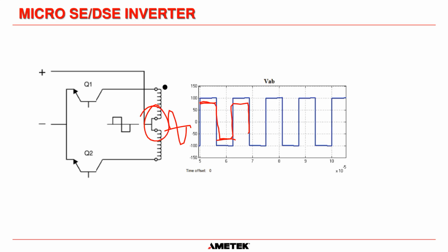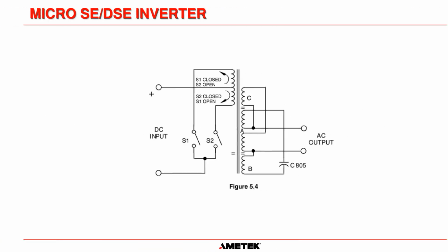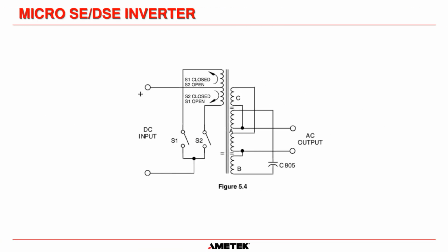So what this transformer does is for the changing DC, the pulsed square wave that goes into the primary of the transformer, although its amplitude will change, the amplitude of the secondary, due to the constant voltage nature of the ferroresonant transformer, the output does not change. Okay? And the easy way to think about it is exactly how it's drawn here, with switches instead of IGBTs. And there's the ferroresonant transformer there.